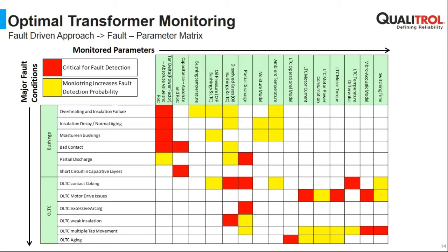But if we use, for example, the heating of the bushing by the transformer, then I might be able to do that by an online method, in order to see the different behavior for wet bushings and dry bushings under different temperatures. So that means the power factor or tan delta, depending on which region in the world you are, is a mandatory parameter.